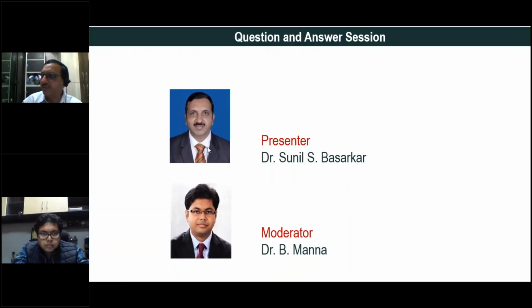up to 600 mm, which means this pile will be able to take load from about 70 ton to about 120 ton. A small diameter pile, a small capacity pile will imply more number of piles will be required. So about 1,000 piles should be a minimum economic criteria for the number of piles we should have for economic deployment of CFA piles.